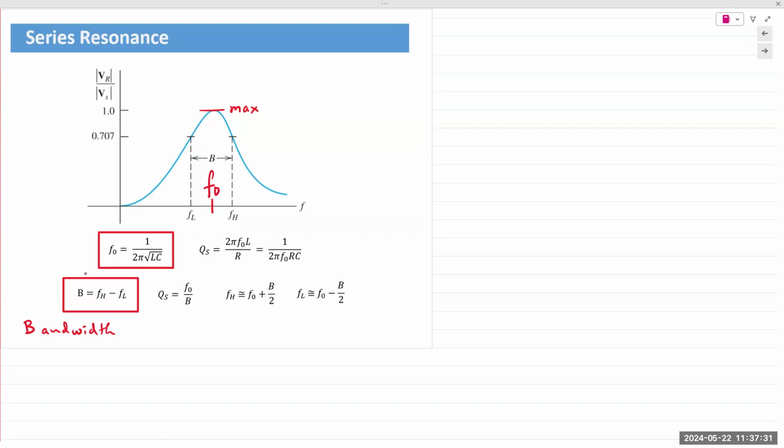Yes. Kind of, yeah. The question being asked is about whether it's low and high of others. But low and high technically just refers to the filtering action. In real life, it doesn't really matter. Yeah. Low and high would be relative, right? If it's a 100 hertz break frequency, 200 hertz would be high frequency. But if it's a 1000 hertz filter, then 200 is low. So it's just relative.